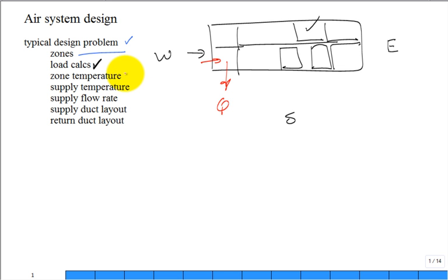So you say that I want to maintain that zone. Typically it's 75 degrees F at 50% relative humidity. Get the temperature before the humidity. If you're at a museum, you got to control the temperature and humidity. You're a hospital, you got to control temperature and humidity. There's some places you got to get them both right, and that's going to cost a lot to maintain and operate that piece of equipment. But typically it's just get it to 75.